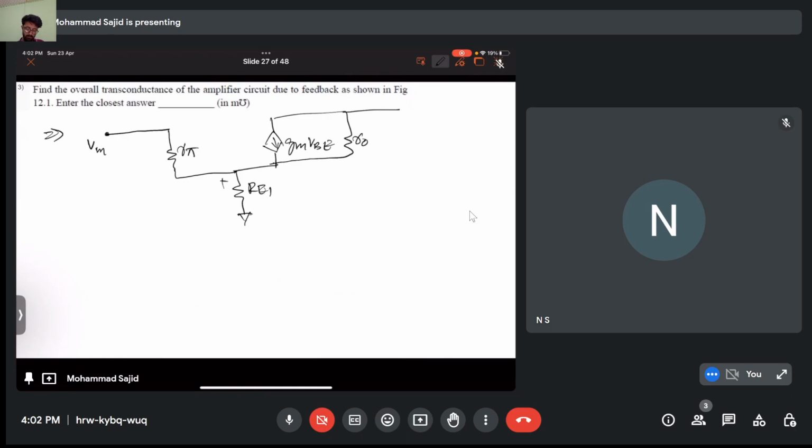This is from this node to this node. This is VF, I naught. Okay, just follow this, and correct me if I'm wrong, so that you will understand. If I apply KCL at this node, what will the KCL be here? I naught will be equivalent to, let's call this node V naught,